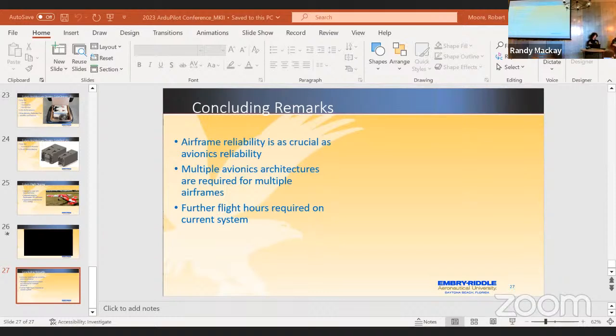Flick into something that puts it into a mode that is safe. And that mode could be simply loiter, and that autopilot might do nothing else other than hold it in position until you figure out what's going on. So keep it safe, keep it simple to start with. And all of this stuff, we definitely want to get there, but step by step by step.